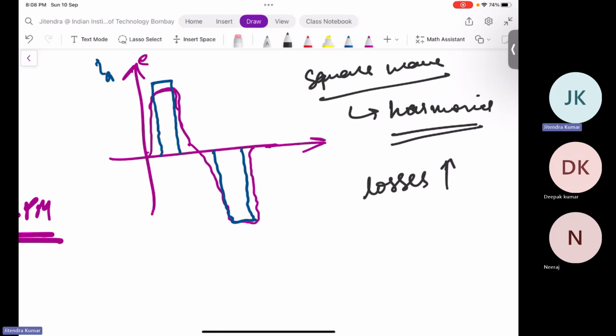So the DC machine is very good from that perspective. But the maintenance is such that it is not able to cater, and your armature MMF is on the rotor. If you rotate it at high speed, your armature will have a tendency to go out of the slots. That mechanical perspective is another issue with the DC machine.